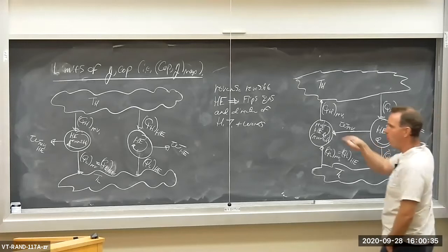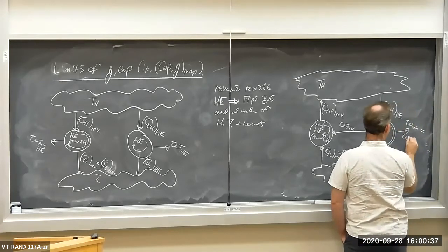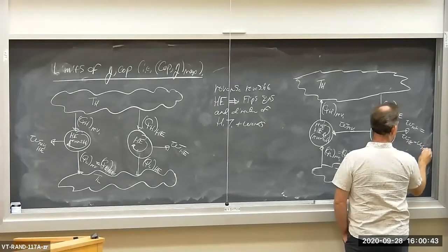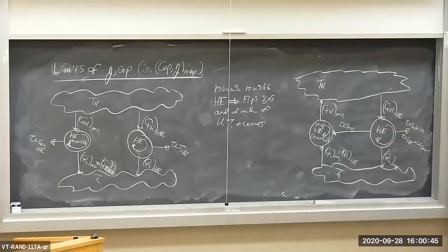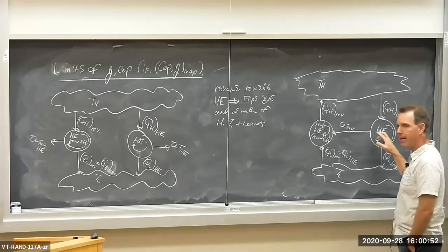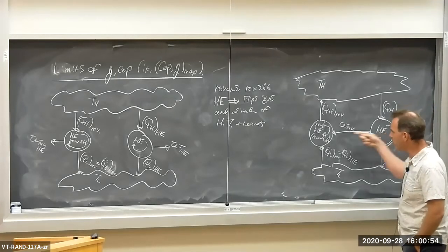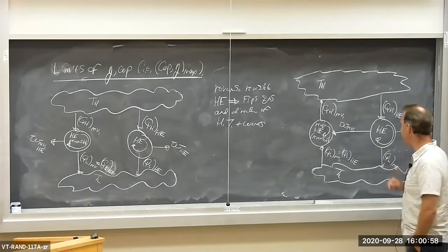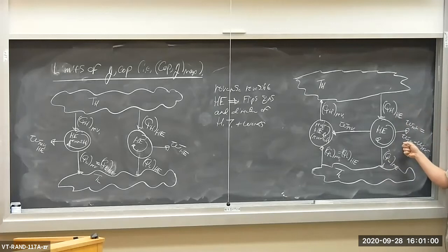It's equal to the old work produced by the heat engine minus W reversed. So the net work produced by the heat engine, some of the work is produced to drive the reversible heat engine. The net is the work produced by the heat engine minus that consumed to drive the reversible heat engine.